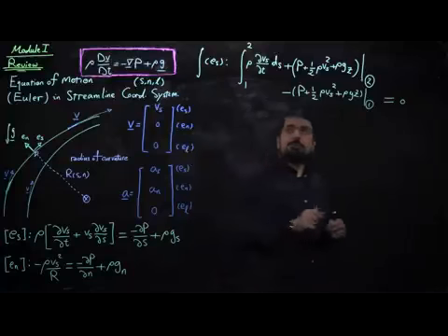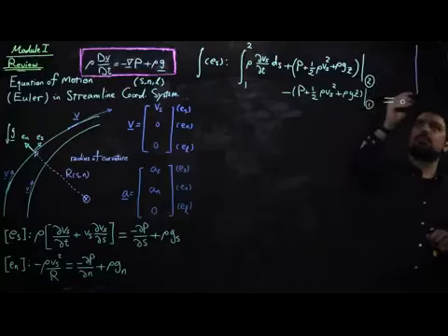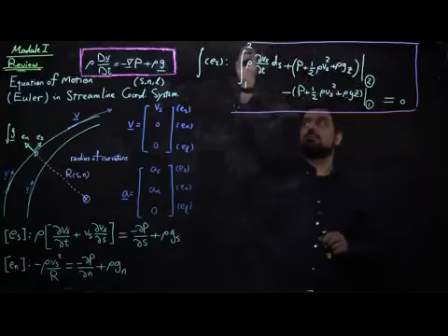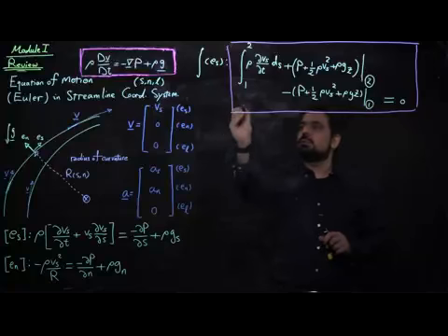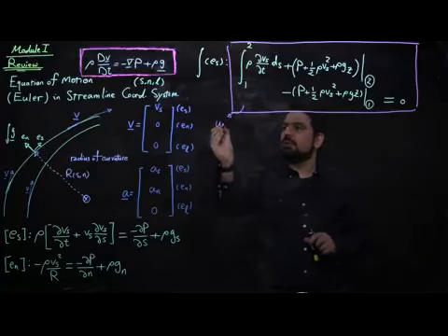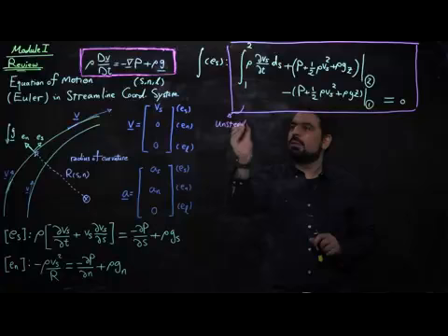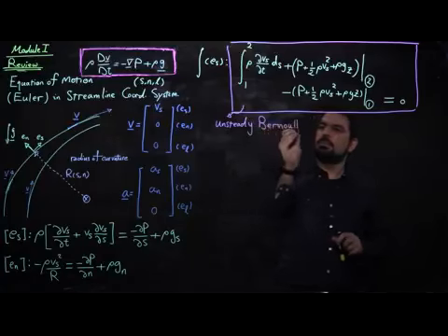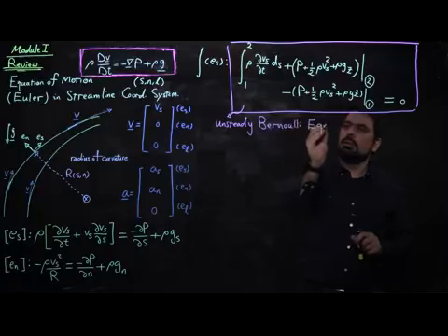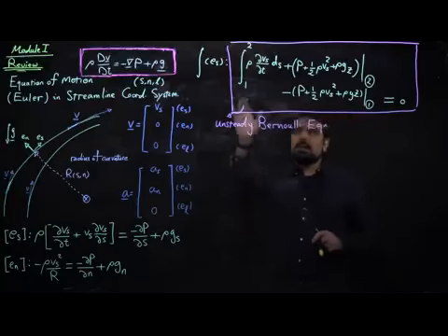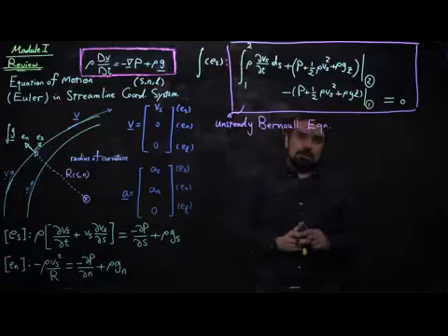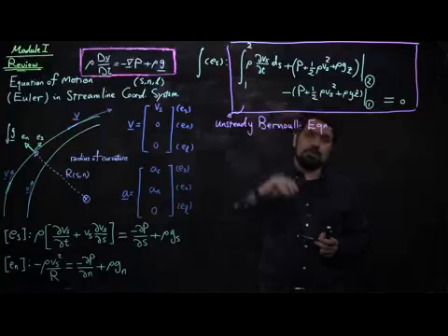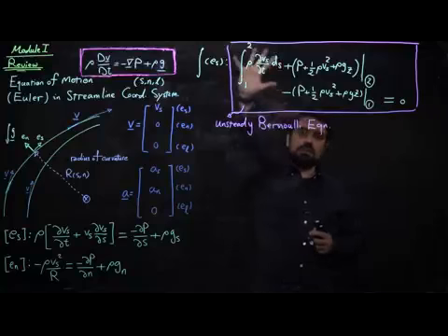And if I put this in a red box, or magenta box in this case, you all should be able to remind yourself what this equation is. This is the general unsteady form of the Bernoulli equation. It simply tells us that there are some transient terms that come due to the unsteady nature of the flow, and we need to integrate them along the entire streamline. But if the flow is steady state, we can ignore them.